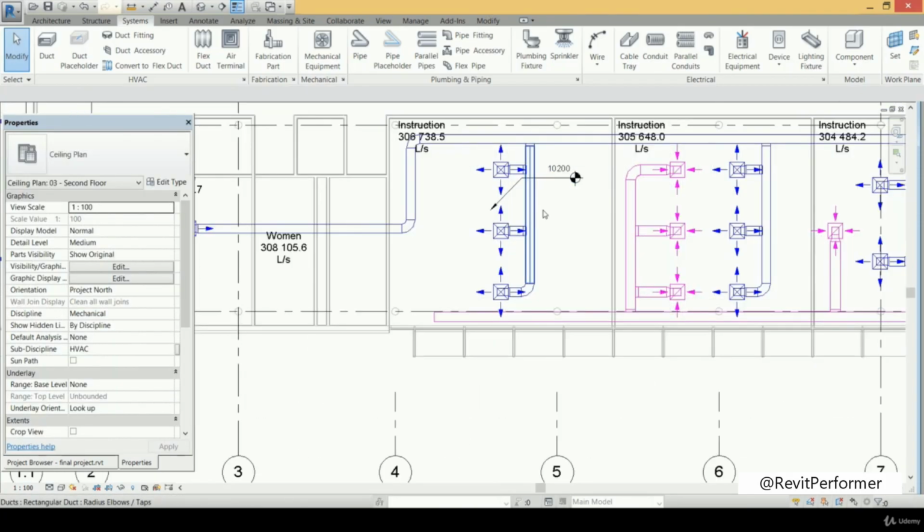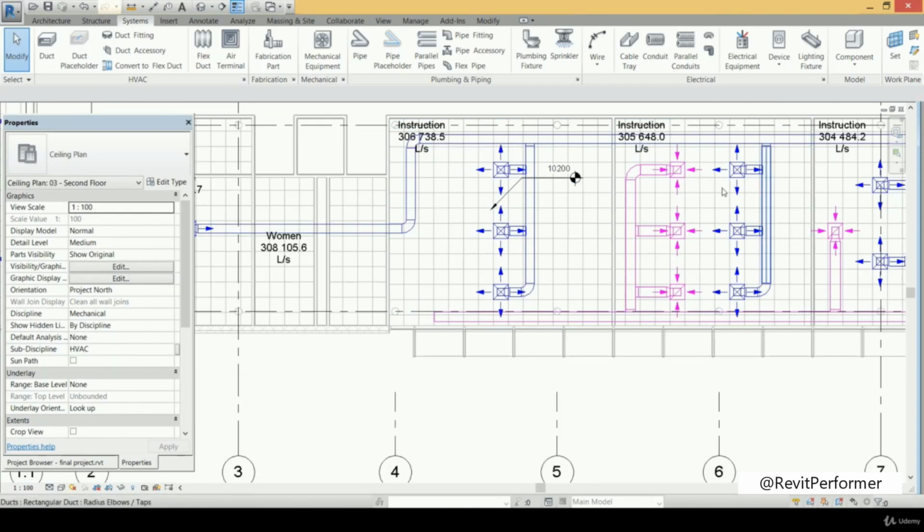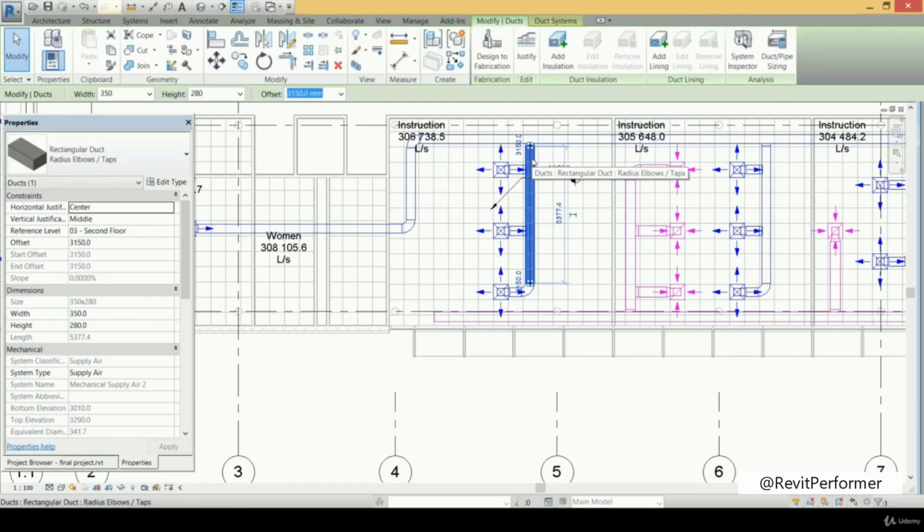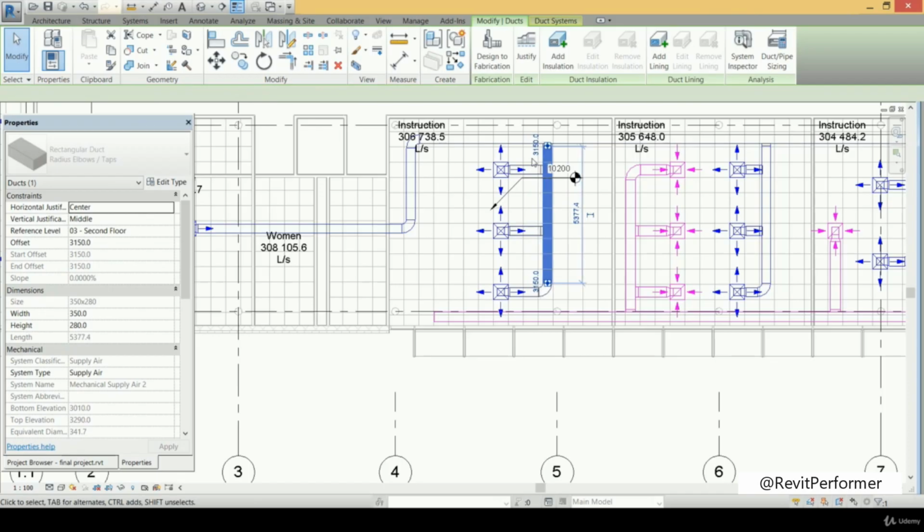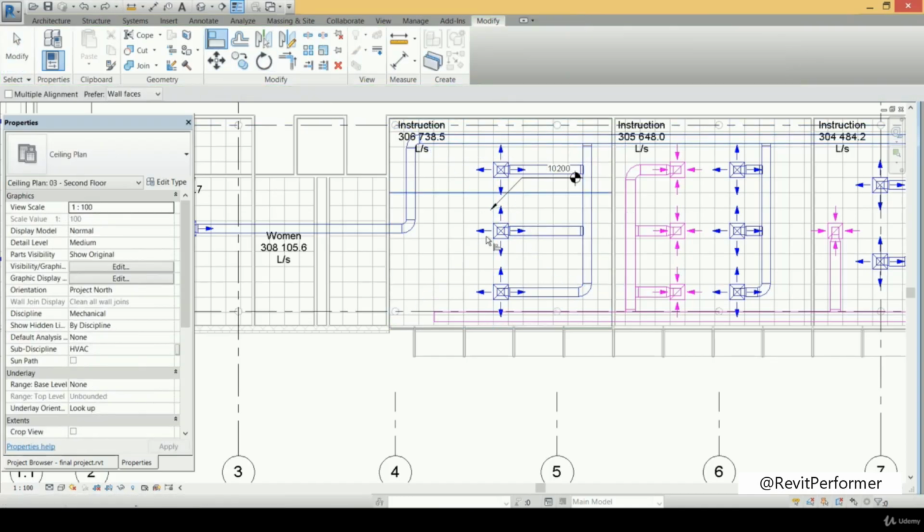Here we will do the same thing exactly as what we did on the third space. So we can drag the duct right here by pressing on the right arrow on the keyboard, and then we align those 3 diffusers with that line, for example. So we go to the align tab and then align those 3 diffusers with that line. So we press on that line and that edge of the diffuser, and the same line and that edge, and also the same line and that edge of the diffuser.